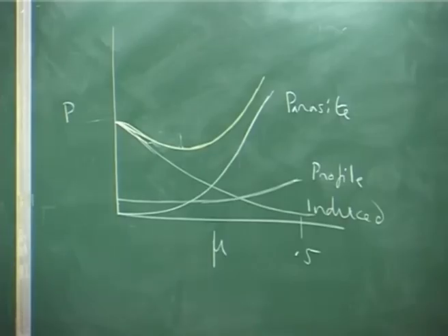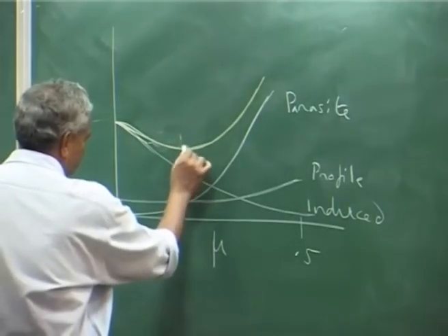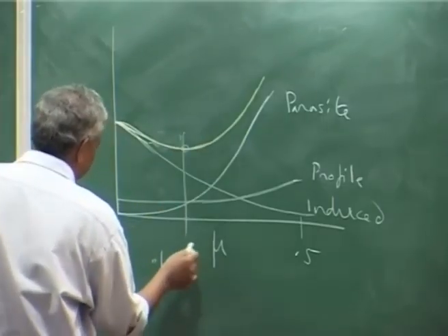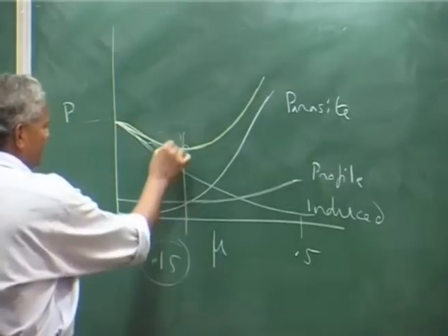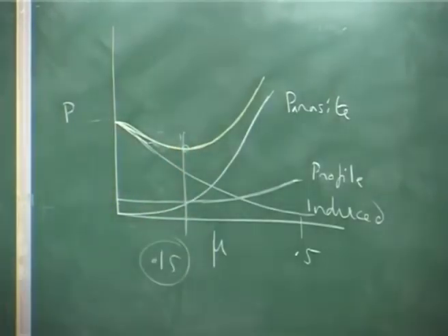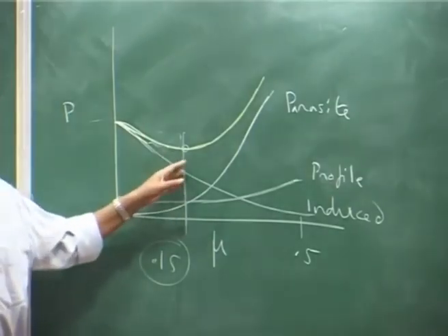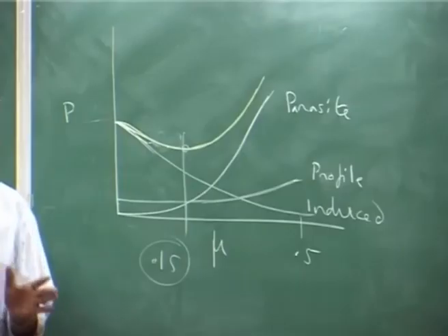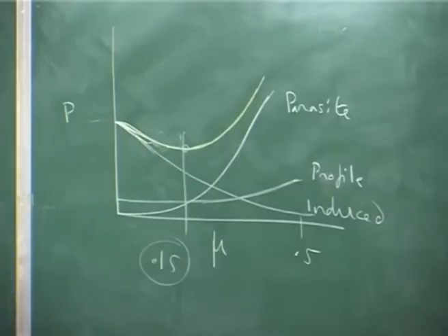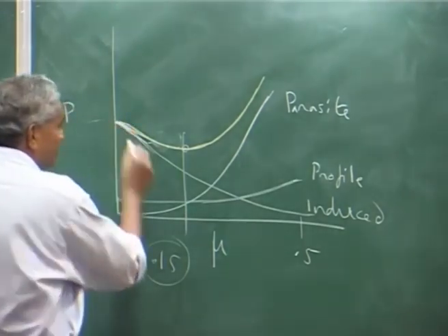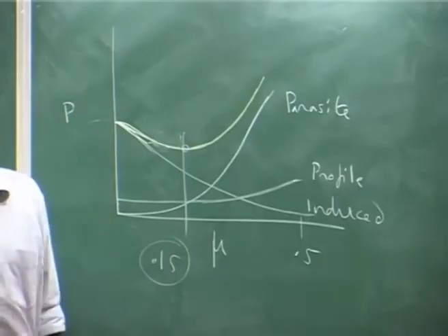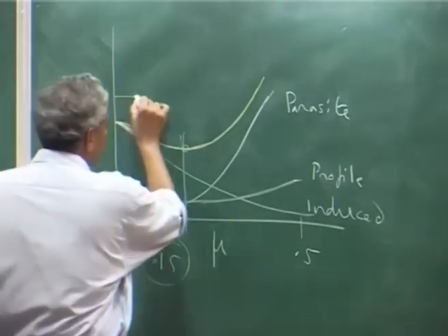Usually it is in the range of, this may be somewhere around 0.15, something like that, around 0.15, 0.1 to 0.2, sometimes 0.11, 0.12, it is in that zone, minimum power for flight. Okay. And then for climb, please understand what is the power available on the helicopter, that you may draw as some line.